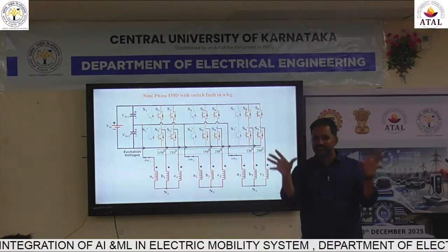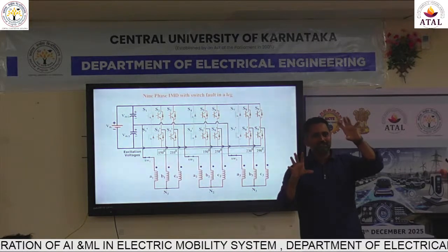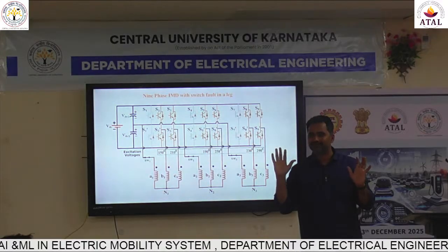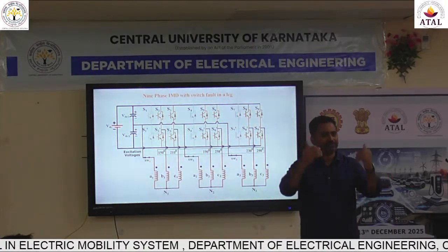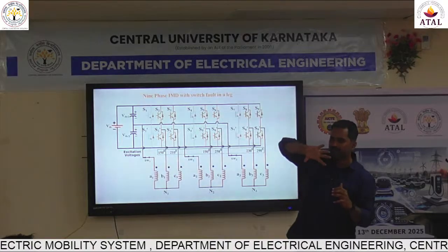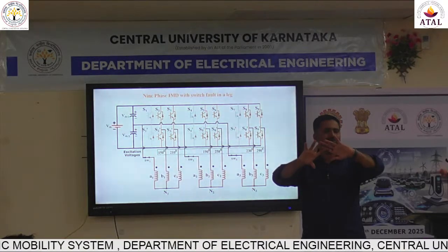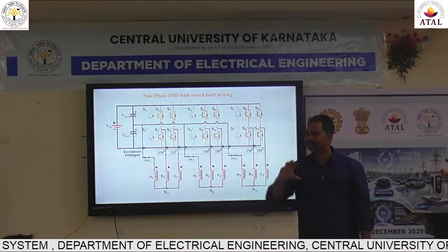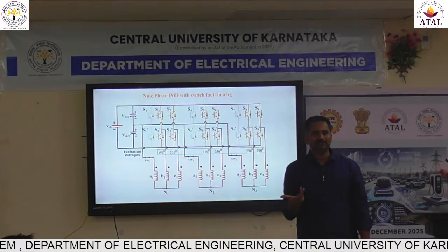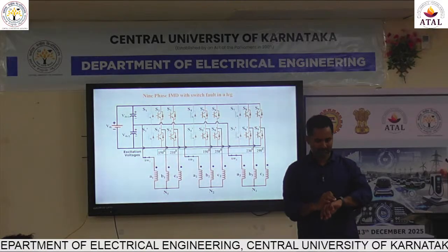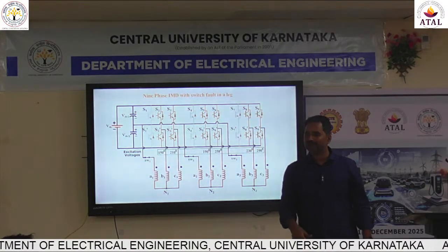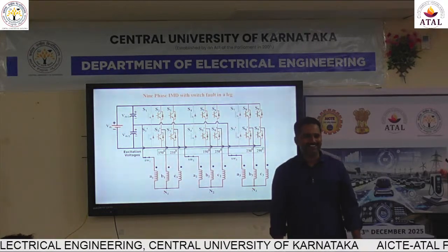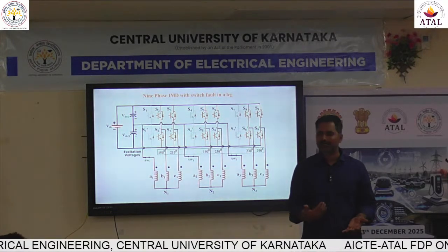Just think in a space of 360 degrees. So for 320 degrees you have a magnetic field, everything is set. For 140 degrees nothing is there. I cannot say nothing, but a weak field or something is there. Then what will happen? The shaft which is rotating will have a lot of torque, and suddenly somewhere there is not enough torque, and suddenly it increases. Those forces, where will they go? When you are driving a cycle, where do those forces go? They go to the knee. Suddenly the jerks have to be absorbed by the knee.